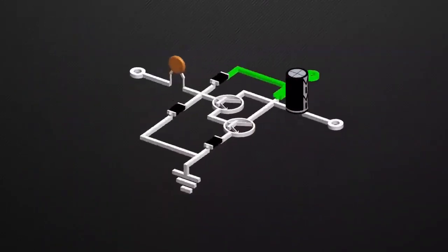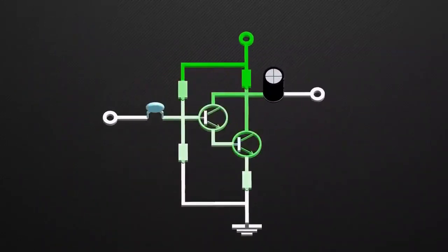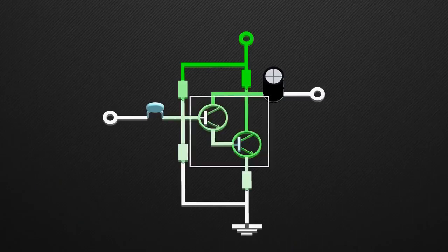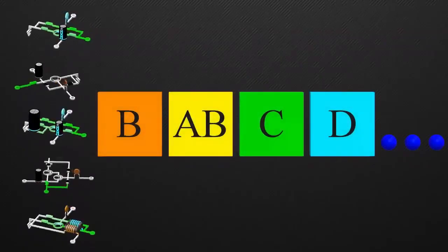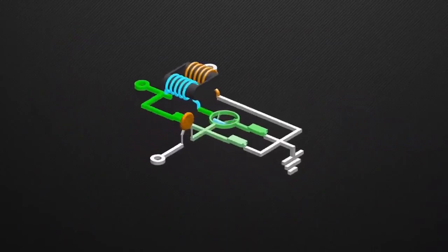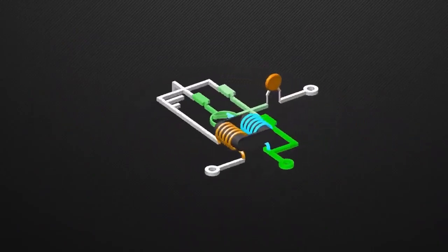This circuit uses the Darlington transistor in place of the single transistor. Darlington transistor is two transistors within a single package, one small pilot transistor and another larger switching transistor. This increases the current handling capacity and gain of the circuit. Also, this provides high impedance at the input and low impedance at the output. This circuit has a transformer, in place of RC, to increase the efficiency of the circuit.